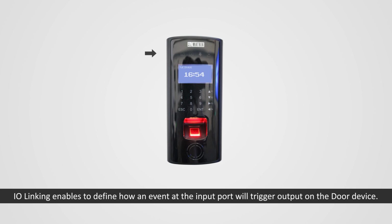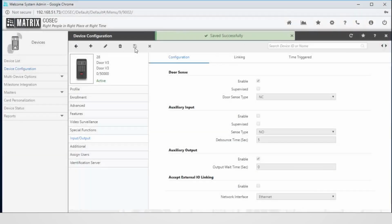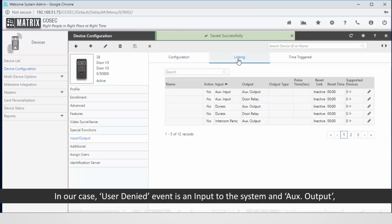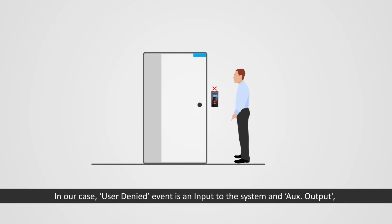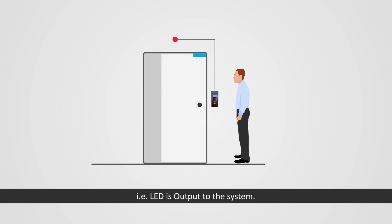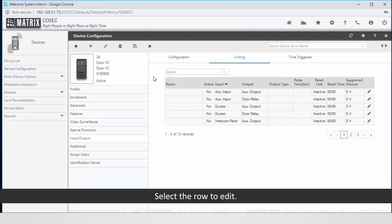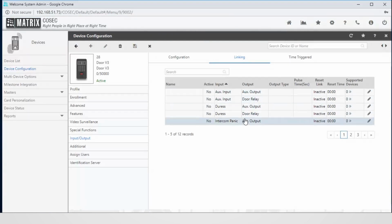I/O linking enables to define how an event at the input port will trigger output on the door device. Go to the linking section. In our case, user denied event is an input to the system, and AUX output, that is LED, is output to the system. Click on the edit icon. Select the row to edit.